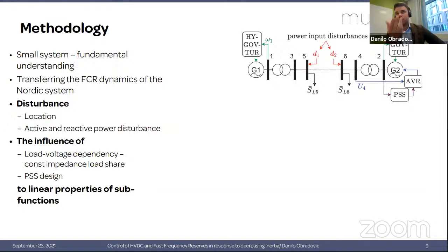But in our case here, we don't have renewables implemented. Here we have constant power and constant impedance load. So maybe you can see this constant power load as something that is also connected to a converter as a PQ, but you don't see this dynamic. In simple software, we can set the PQ load, and the linearization works fine or satisfactorily.